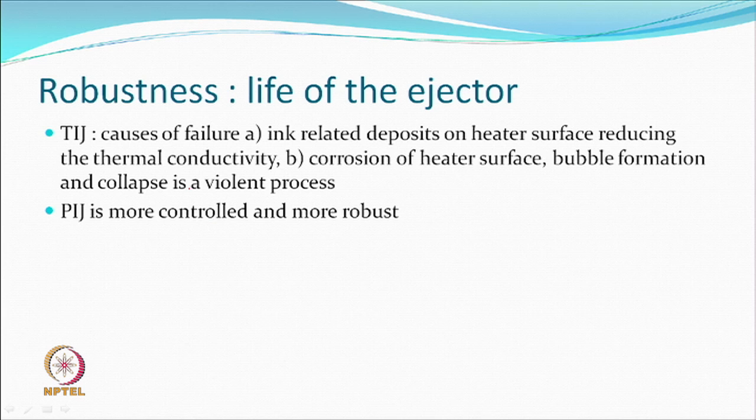So for pigment based inks, piezo based systems will obviously be preferred, which do not do any heating. Robustness, life of an ejector: thermal inkjet can cause failure due to ink related deposits on the heater surface, reducing the conductivity, that is, the heat generated is being blocked by something which has been deposited on the surface of the heater.